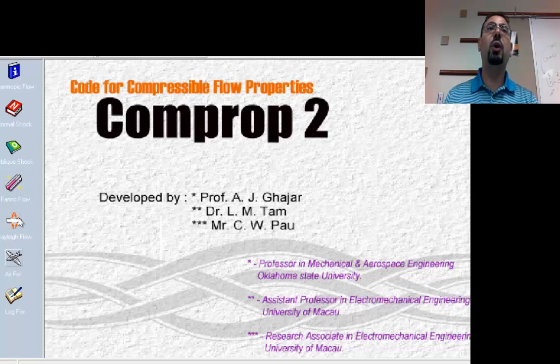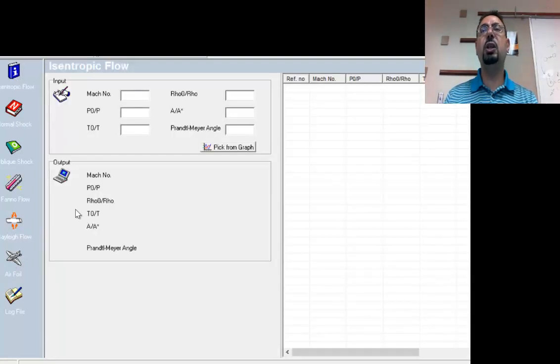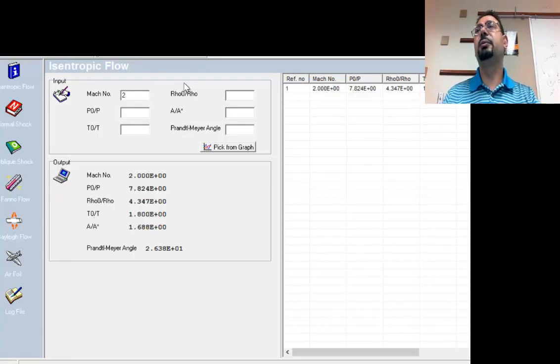Together also with design of airfoil. So for example, chapter 3, what we did right now, what we said Mach equal to, right? And the gamma 1.4 is here. If you want to change the gamma, change over here and just hit enter. And that's T naught over T, 1.8. So the 1 over the 0.556 is 1.8. So that's T naught over T.